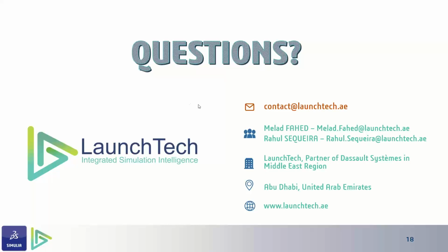So one question is, how much computational power would be required for running a similar simulation like this one? Well, it depends on the mesh. Usually CEL is computationally more expensive than SPH and then Lagrangian. This is because in the domain that Rahul created, the mesh has to be extremely fine, even finer than the Lagrangian model, because the material has to flow through the mesh.